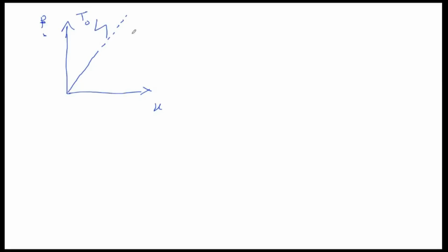And for that vibration period, you can compute the acceleration that this single degree of freedom system will experience, the response acceleration, and from that acceleration, you can calculate the corresponding elastic force, as well as the corresponding deformation. Okay?